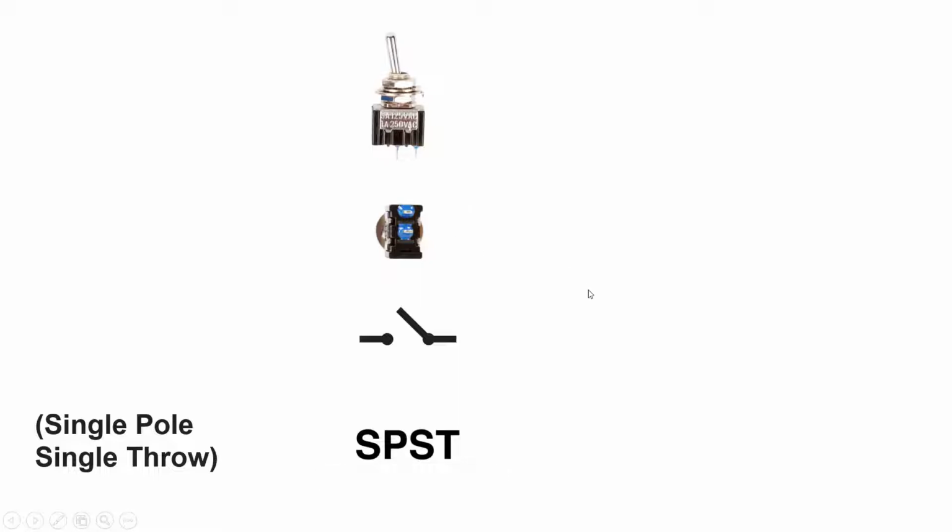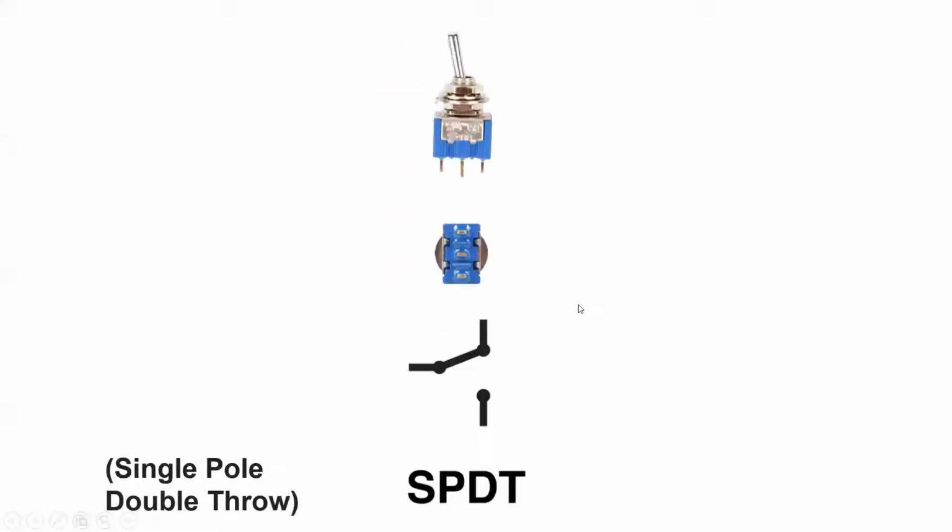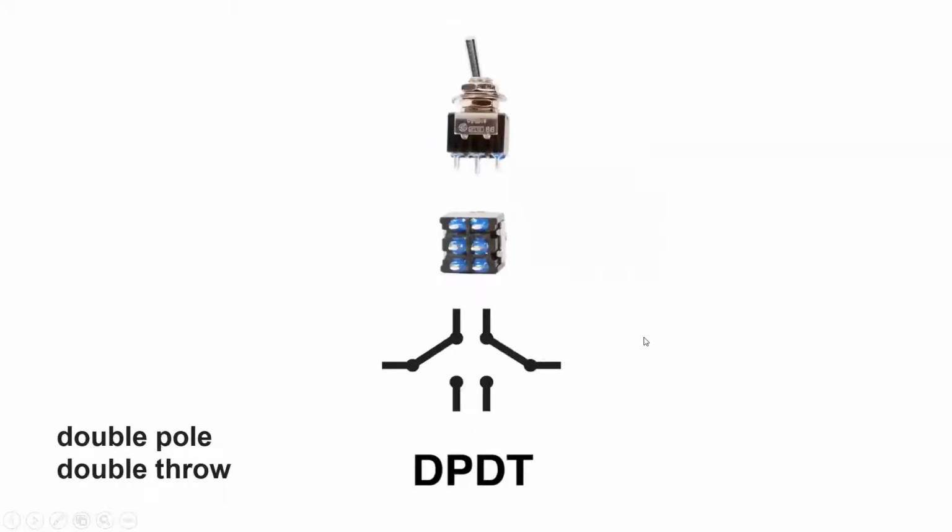So the second switch that we need to know is the single pole double throw switch, where you have a single pole which you operate and you can control 2 points. This is point number 1 and this is point number 2. If you follow the video, like the GIF file, you can control the 2 points, right? That is why we call it single pole double throw. The same way, the next one we have is double pole double throw. So we call it a DPDT switch.